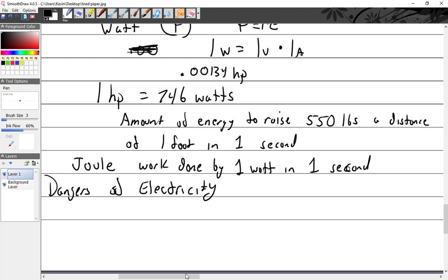In fact, I even had a conversation. We bought our new machine. I don't know if you guys have even seen it over there. In fact, I need some help moving it. I asked Magnaflex, how come it's safe to hang on to something where that many amps are flowing through it? They said, well, first of all, the voltage is so low it can't break through your skin. And the parts that you're working with, the resistance is so low that it doesn't see you.